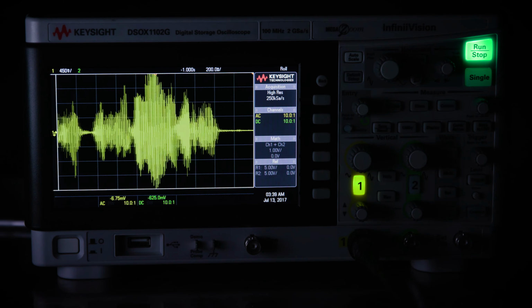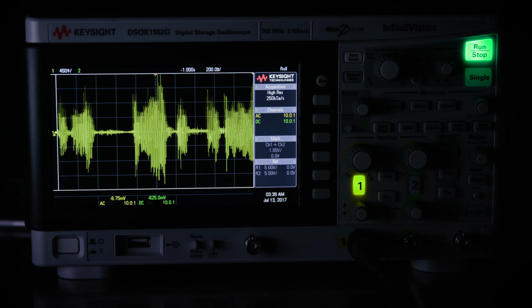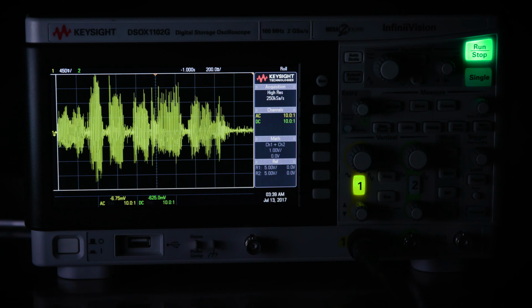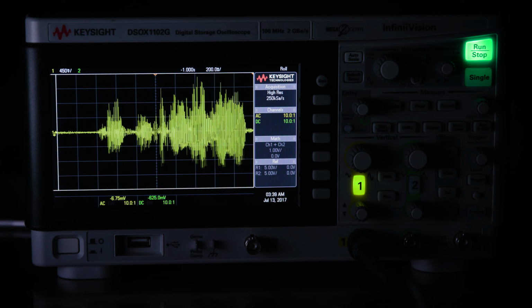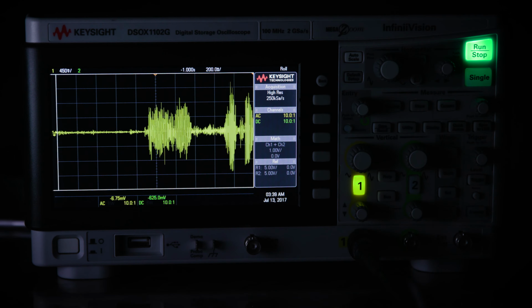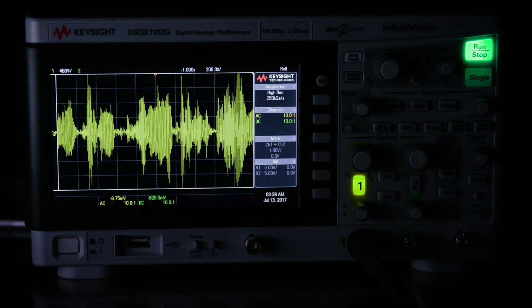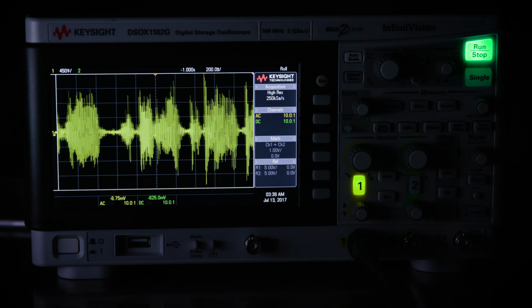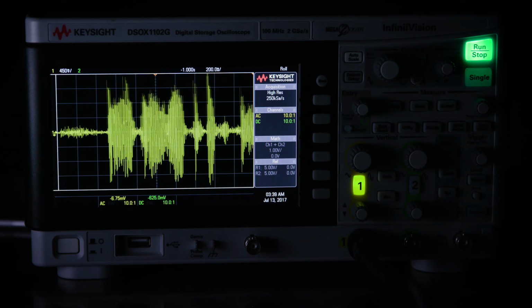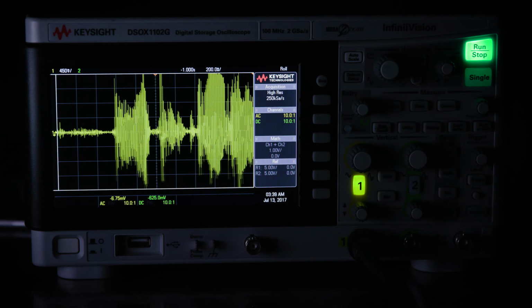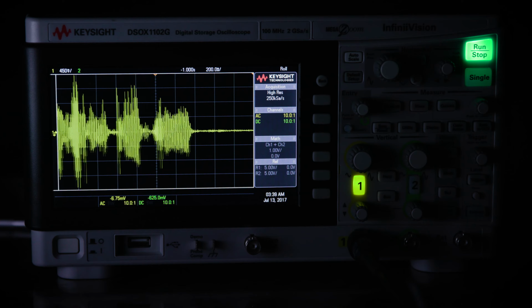And normally, we have a tendency to oversimplify the specifications of an A to D converter into sample rate and bits. Those are the two easiest ways to think about how accurately we're measuring the time and how accurately we're measuring the voltage. Banner specs, right? But you peel back the onion a little bit, and there's all kinds of other secondary things you need to worry about. Number one being bandwidth and frequency flatness, but also your noise.